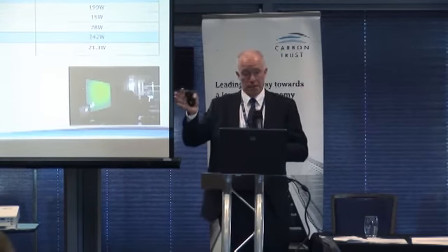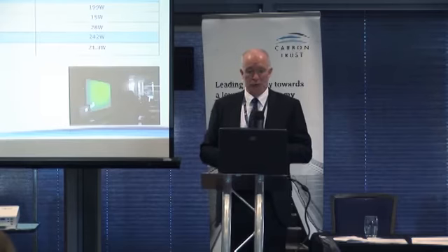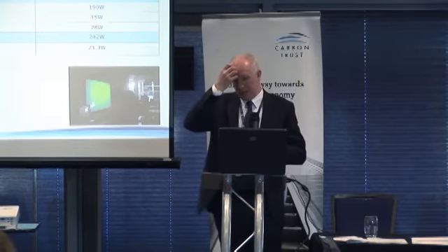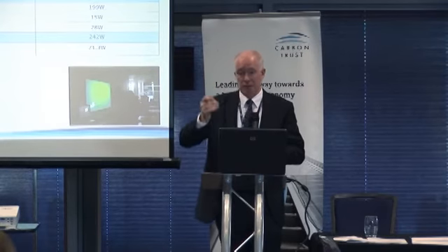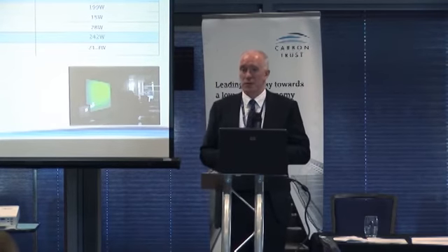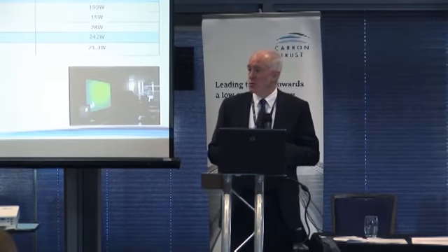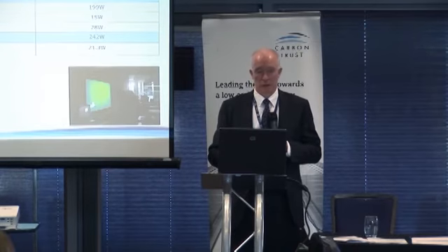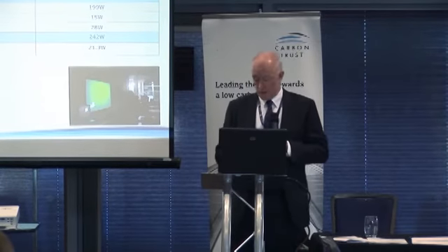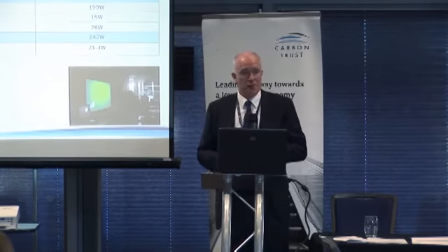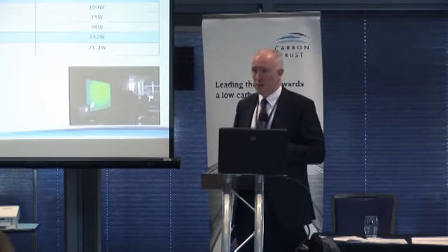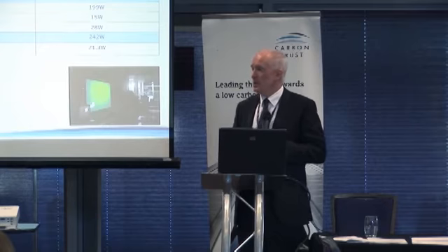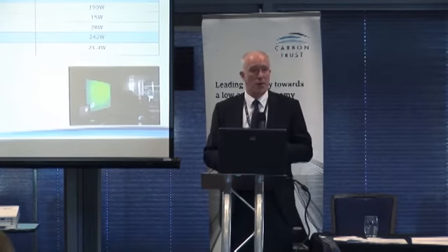Talking about schools and going back to the points that have been made earlier, whiteboards came in, what, 15 years ago, something like that? And I had a head teacher who rang me up because their electricity consumption had gone up so much when they put them in. They couldn't believe their electricity consumption in their single entry primary school had gone up by 20% because they put whiteboards in. Not greatly surprising. You've got perhaps a maximum of half a kilowatt of lighting in a school classroom, and you plonk in 200 watts of whiteboard equipment, so it's going to go up by a third.